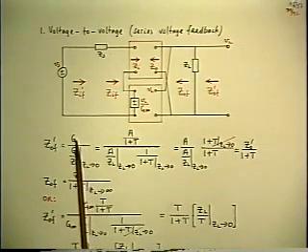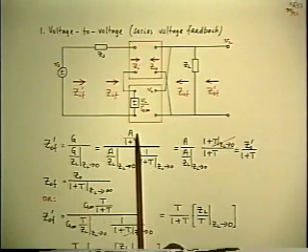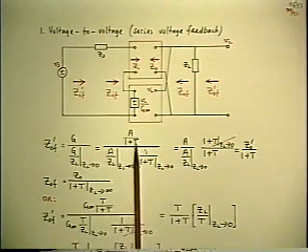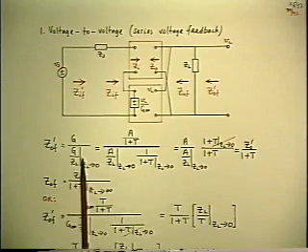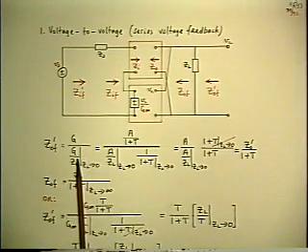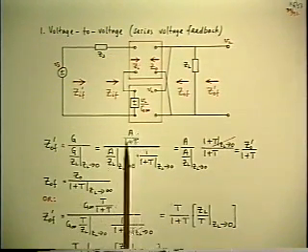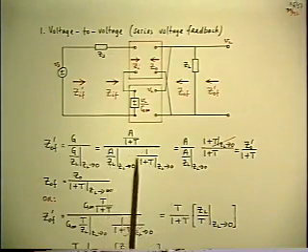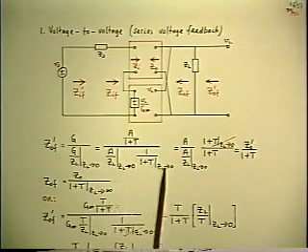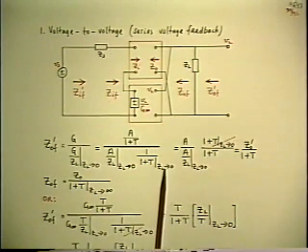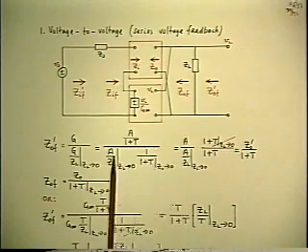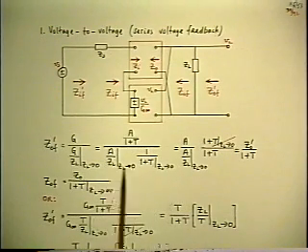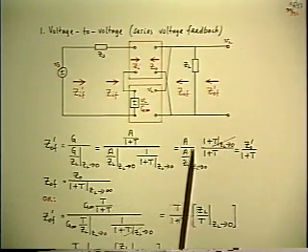All you have to do is substitute the known relationship for the G in terms of the open loop quantities. So you could substitute A over 1 plus T in both places. But you can take the limit factor by factor. So G has two factors, A and 1 plus T. So I've separated the two factors, and you can take the limit independently. Then I've collected together the A from the numerator and the A over ZL with the limit from the denominator, and put that out front.